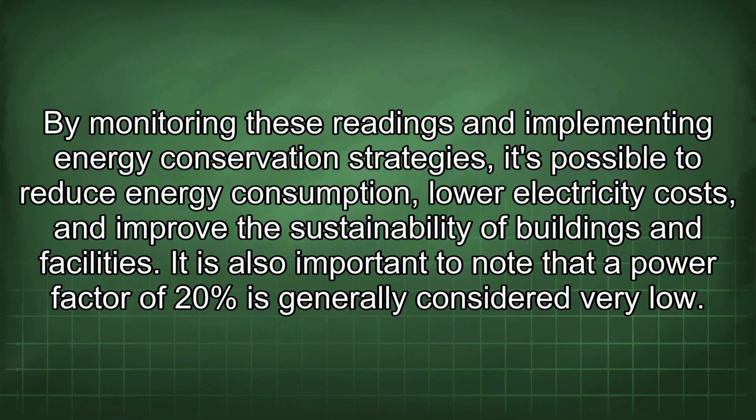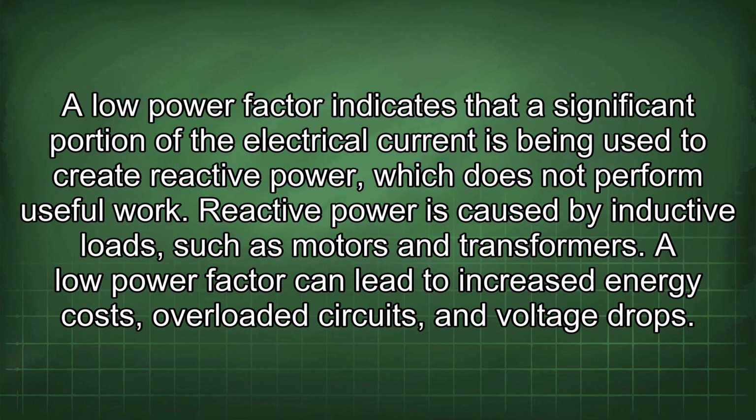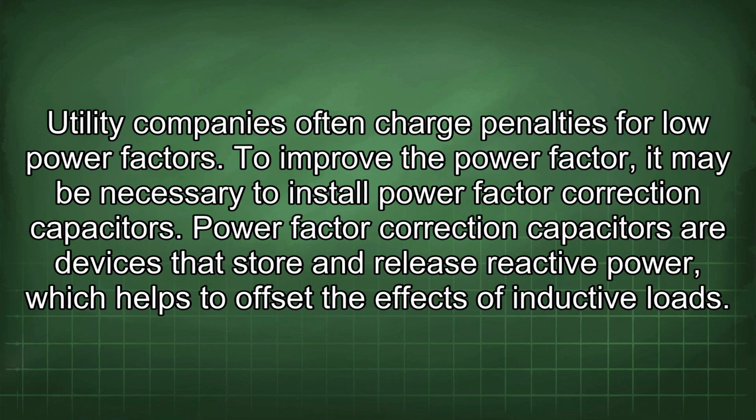It is also important to note that a power factor of 20% is generally considered very low. A low power factor indicates that a significant portion of the electrical current is being used to create reactive power, which does not perform useful work. Reactive power is caused by inductive loads such as motors and transformers. A low power factor can lead to increased energy costs, overloaded circuits, and voltage drops. Utility companies often charge penalties for low power factors.